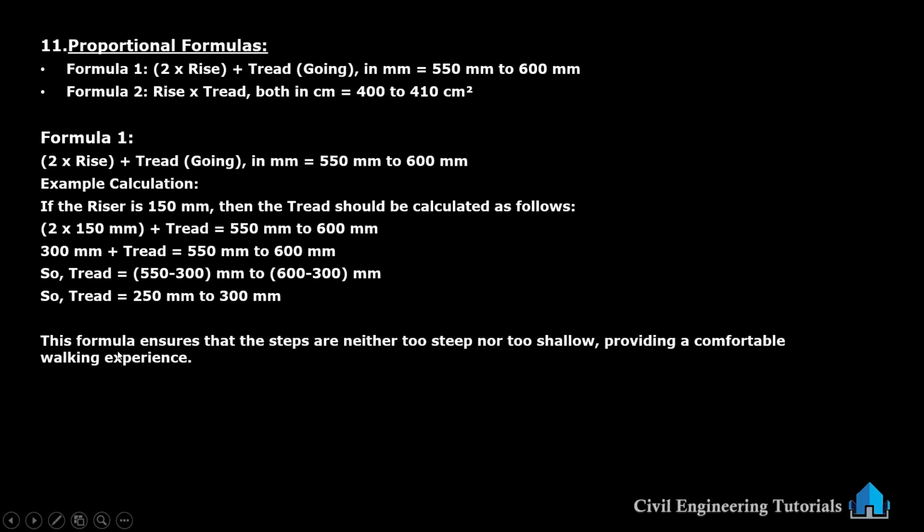This formula ensures that the steps are neither too steep nor too shallow, providing a comfortable walking experience. So now tread is 250 mm to 300 mm, which fits the formula. Now I'll check the second formula.